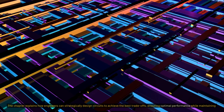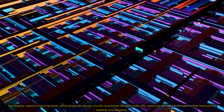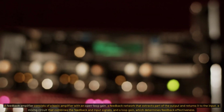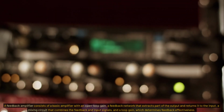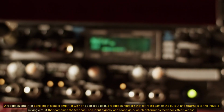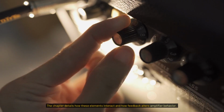The chapter explains how engineers can strategically design circuits to achieve the best trade-offs, ensuring optimal performance while maintaining stability and reliability. A feedback amplifier consists of a basic amplifier with an open-loop gain, a feedback network that extracts part of the output and returns it to the input, a mixing circuit that combines the feedback and input signals, and a loop gain, which determines feedback effectiveness. The chapter details how these elements interact and how feedback alters amplifier behavior.